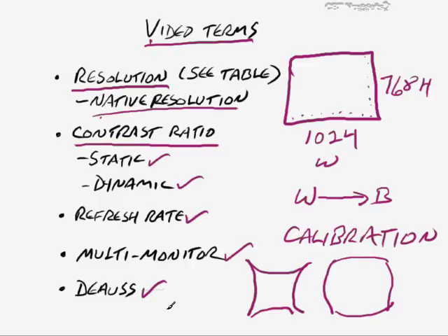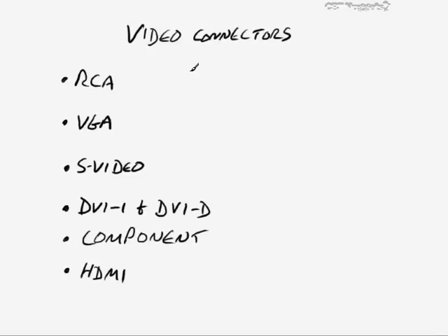Well, most of the monitors, if you look through the menu systems on the buttons on the monitor, there will be a degauss button, and when you press that, that may help to alleviate this situation somewhat. And then there are also probably additional controls that you can fiddle with that will allow you to do this as well. And it just changes the way that the electron gun and all of the associated components internally will focus the screen.